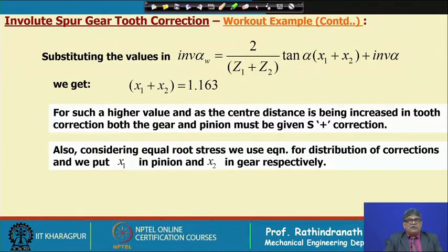So, from the material point of view the consideration will be different, but usually gear materials are taken as slightly weaker, but not very weak. So, possibly that formula can be safely used and we will arrive at the tooth thickness such that they will have more or less equal strength.